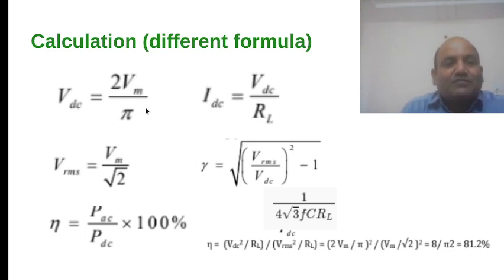which is because of the low resistance of the secondary of your transformer and the on-resistance of your diode itself. So you will get a difference between the VDC you are measuring across the output by your voltmeter and the calculated value; both will show different readings.